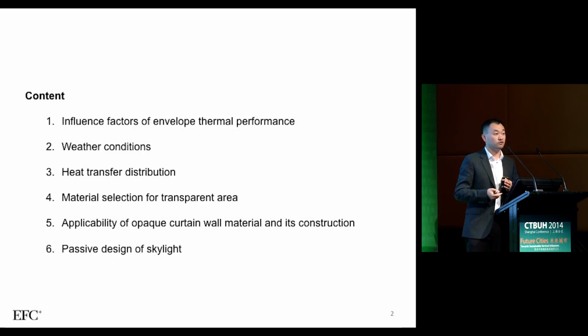So when we design the facade, we suppose that the facade encloses the whole building very well. So the contribution of the convection is very low, and the two most important things are conduction and radiation. Let's say the content of the lecture is about these three points.